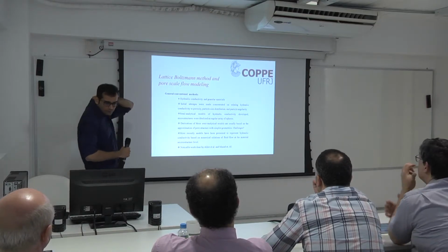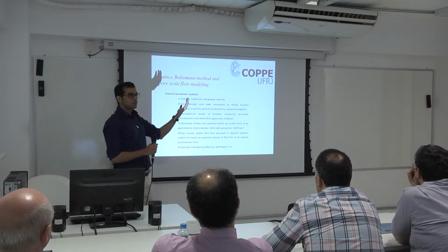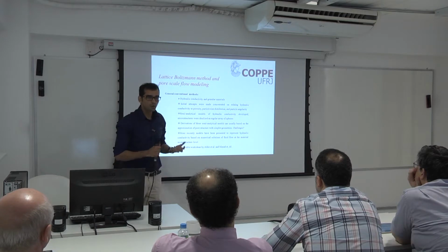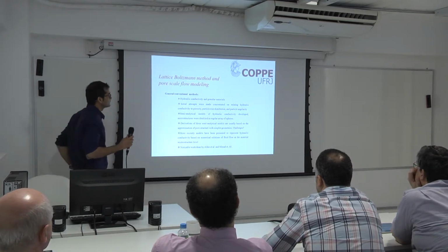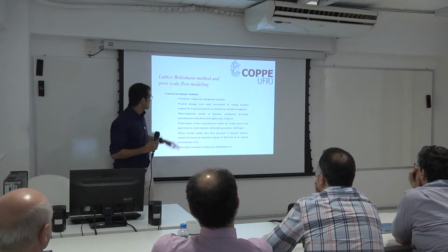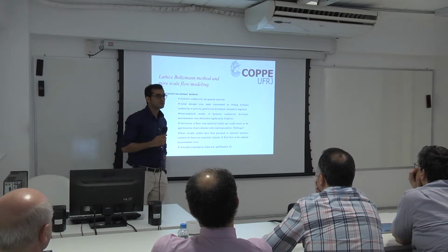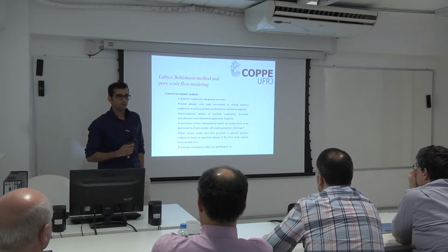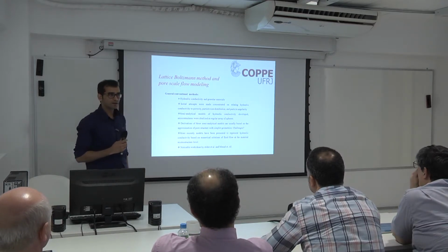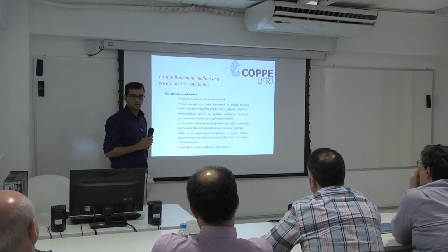Now, the lattice Boltzmann method and pore scale modeling, the core ideas. The hydraulic conductivity and granular materials. What is hydraulic conductivity? It is simple: permeability of the particular fluid that you are studying in your pore or in the porous medium.